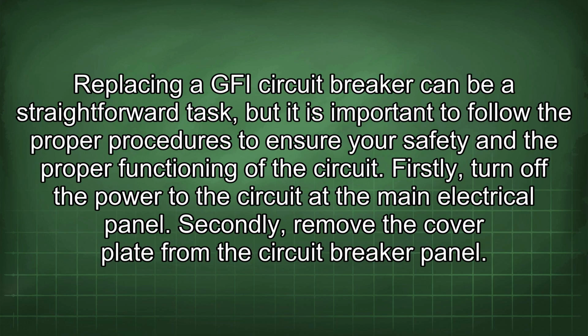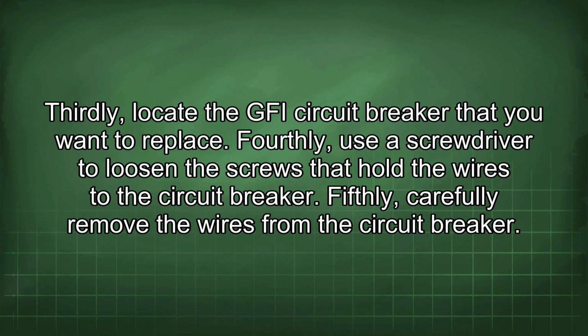Replacing a GFI circuit breaker can be a straightforward task, but it is important to follow the proper procedures to ensure your safety and the proper functioning of the circuit. Firstly, turn off the power to the circuit at the main electrical panel. Secondly, remove the cover plate from the circuit breaker panel. Thirdly, locate the GFI circuit breaker that you want to replace.